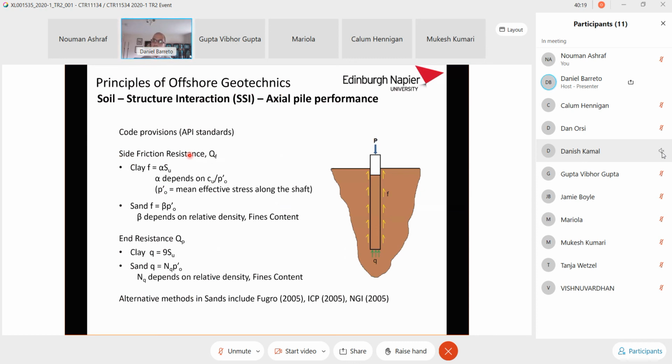And assuming that everything goes well, you will spend maybe 1 hour per meter of penetration. If you can reduce your design to be able to afford a pile with a meter less of depth, and you're saving that times 200 piles, on that just simple saving, you are making a saving of 200 million pounds.